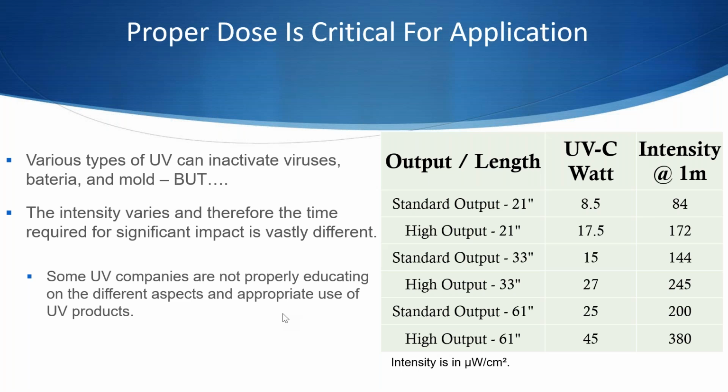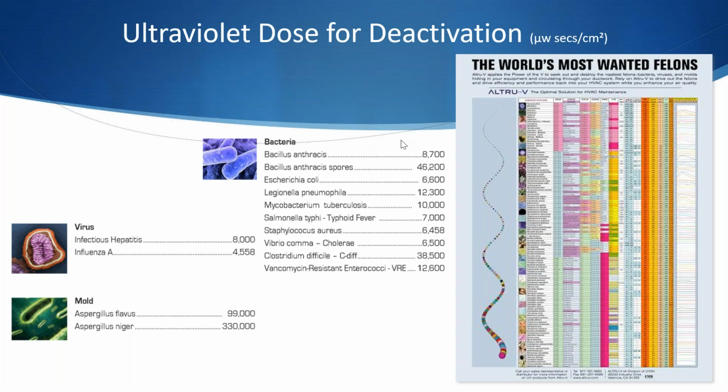Now when we're applying it in the duct, a lot of people are asking us for quotes at very high velocities. We can accommodate for that. UV companies broadly can accommodate for that velocity, but really should keep it to 1,500 feet per minute or less, realistically, where the quantity of lamps and the application of lamps starts to not make sense after that, because it's so much required to accommodate for that lower residence time with the lamp. So dosage is a really important part of UV to understand, because it is very scientific and there are very clear answers. We just need to understand all the factors to it.